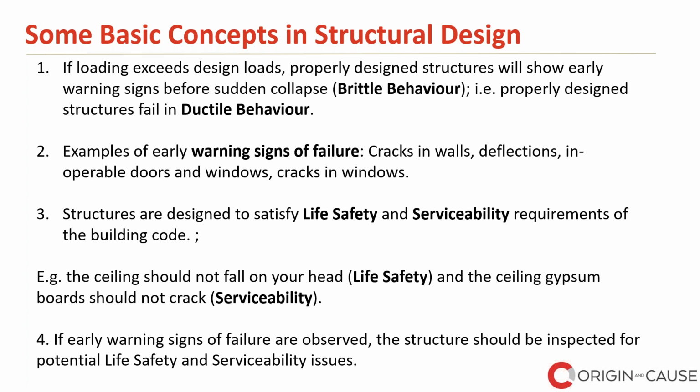And also, structures are designed to satisfy life safety and serviceability requirements of the building code. What I mean is, let's say the ceiling should not fall on your head, no one wants that. That's a life safety concern. At the same time, the ceiling gypsum panels should not crack. That's a serviceability issue. Or the windows or the doors should be operable. If they become inoperable after some time, that's a serviceability issue.